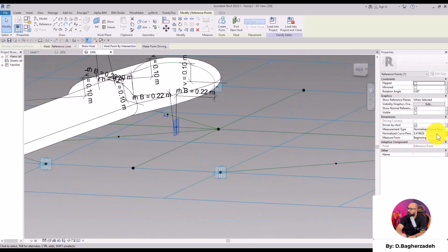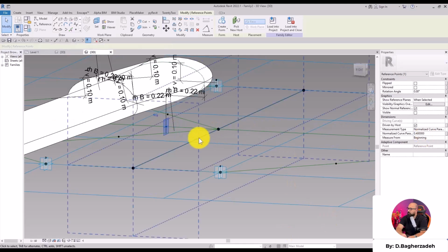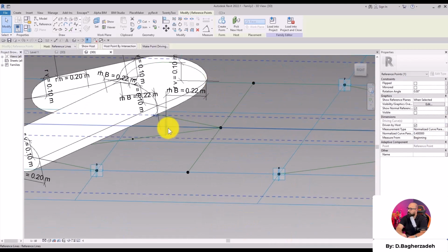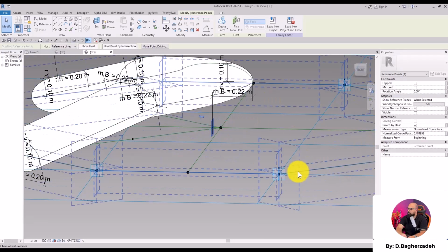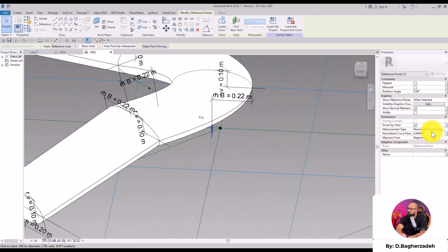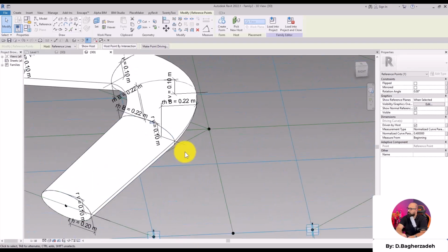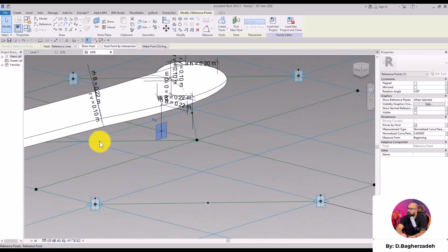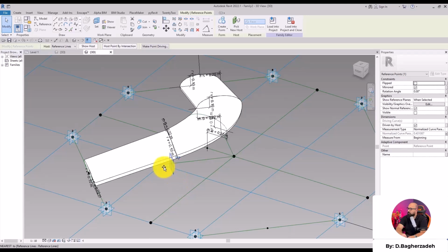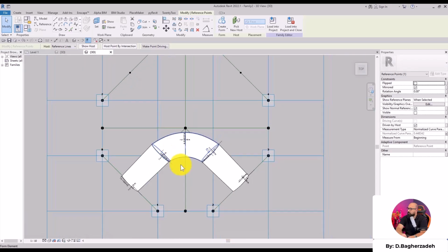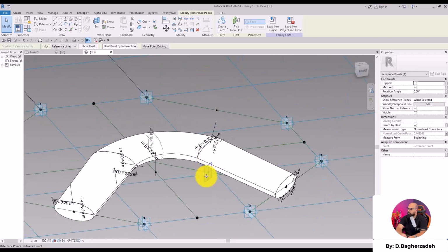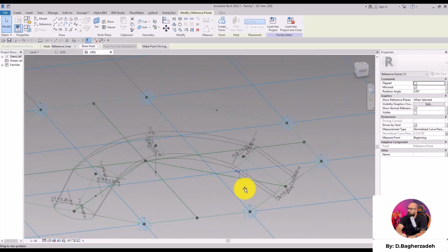Now, I'm going to set the NCP on 40 first. Okay, moved like this. When we move it towards this side, it gets closer to 0.5. Oh, and by the way, we need to do something for this side as well, guys. And, well, as you can see, this is quite deformed, so let's set this back on 40 again. Now let's try adjusting these manually a bit, like, for example, we should move this downwards. And then if we move this closer, we'll get a better form. Okay, now let's move these points and check these again.